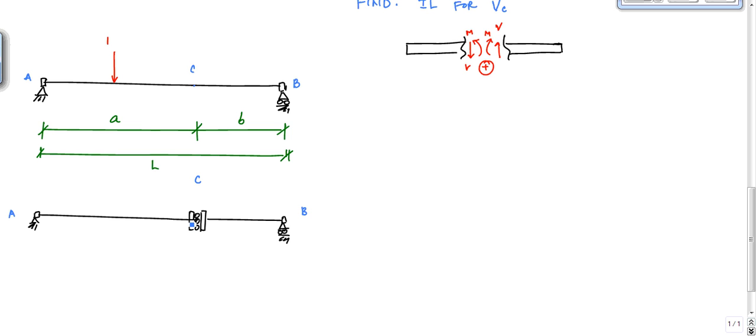So if I have internal shear that I want to remove, I have to maintain the ability to transfer axial forces and moments across this connection. That's what these blocks do. And these rollers. So essentially this thing can only slide up and down, but it cannot rotate right here.